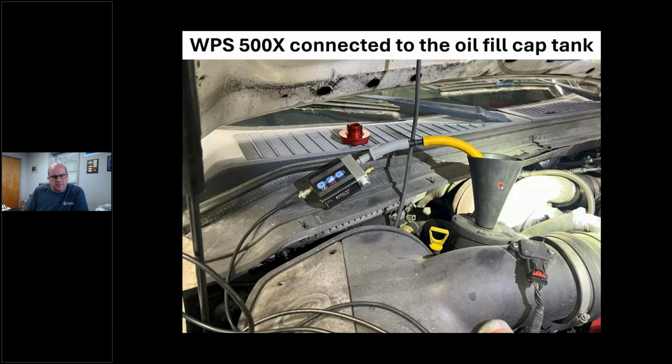You probably could go on the dipstick tube with this too, and you'll see the star of the show is this spark plug boot. I love old spark plug boots on my transducer because I learned this many years ago from a friend of mine that these things will go over anything, okay? And when I put this thing over anything, it works great. Okay, I can put it over a dipstick. I can put it over PCV valves.